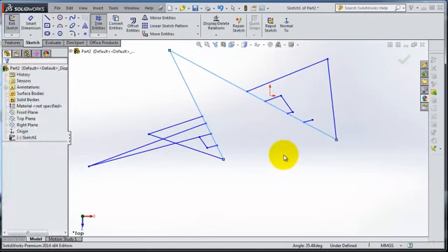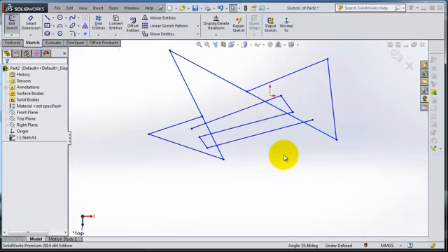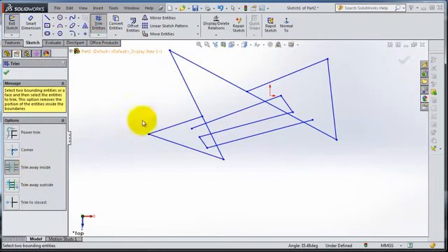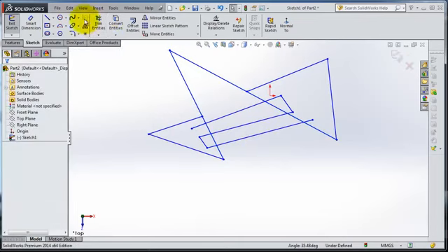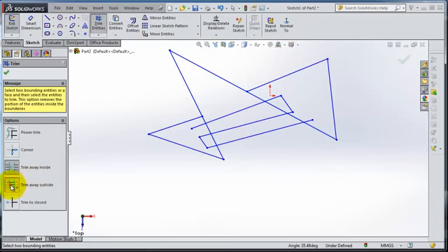So Control C. So let's trim away inside. Select that line, this line. Now you are able to trim everything in between these 2 lines. If you select that, so you are trimming. Control C. Let's try the next type, trim away outside. This line, select. So now you are doing the opposite, trim away outside.